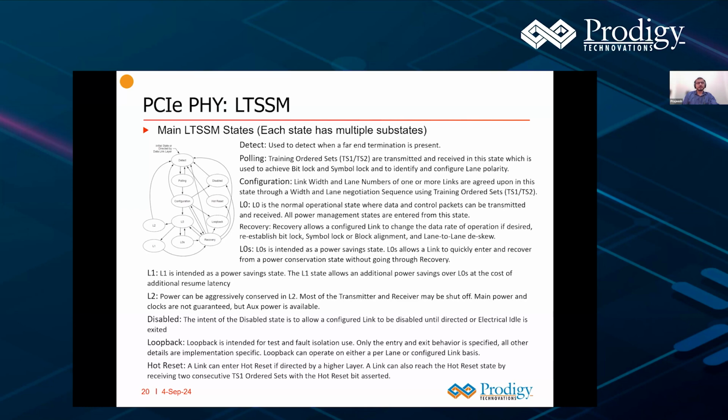There can be multiple links as well. If both support x4, it can operate as 1 link of x4 width, or 2 links of x2, or 4 links of x1. All those combinations, whatever is supported in the spec, are possible. All that is established during the configuration state.